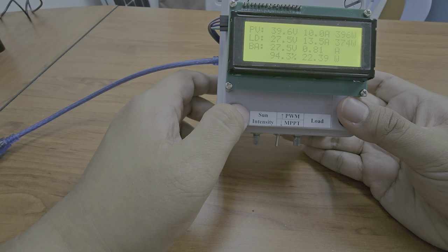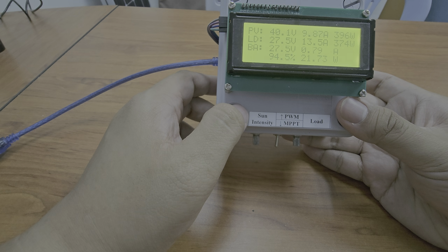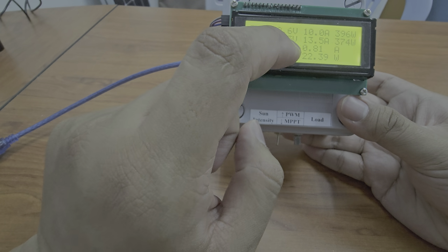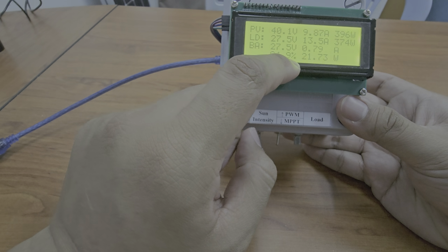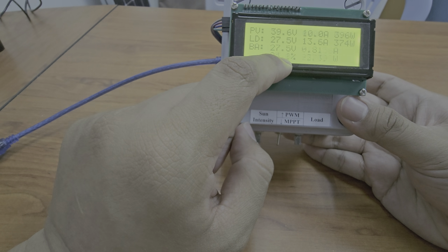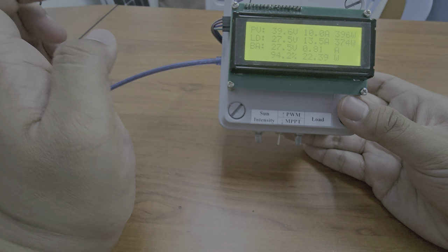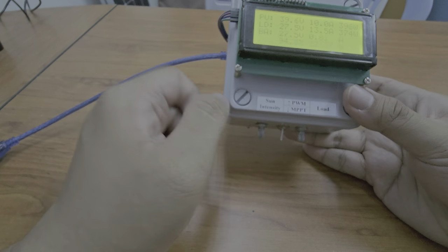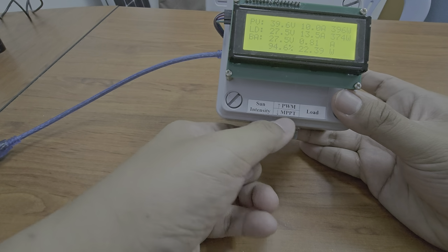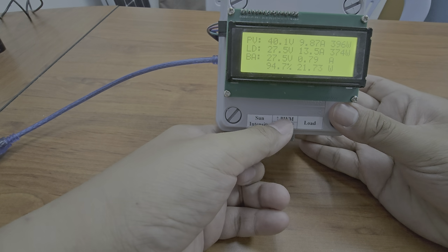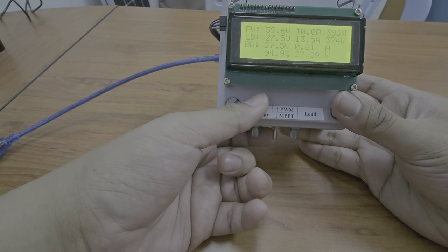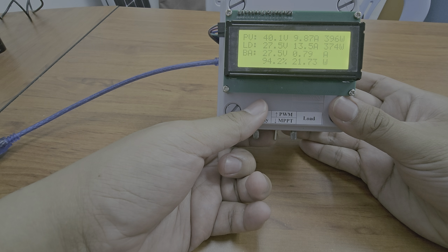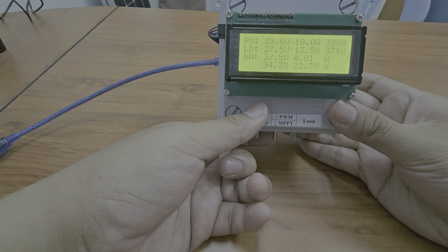If you check the charge controller, it is basically floating voltage. It tries to float around a specific voltage. In this case, the SOC is around 95%, but in reality it will use voltage instead of SOC. So basically that is the difference between PWM and MPPT. I hope you can understand this. If not, you can try to look at the theory first before you continue with this.